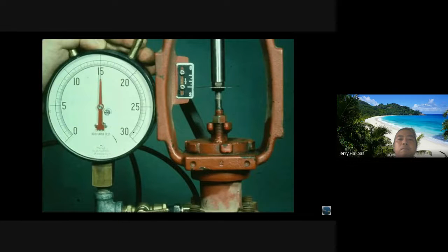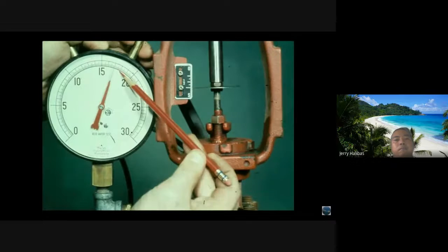The air close valve is checked in the same manner. However, the valve will seat at 15 psi rather than 3 psi. Slowly apply air pressure to the valve. Observe the valve stem travel. Note the input pressure needed to seat the valve.